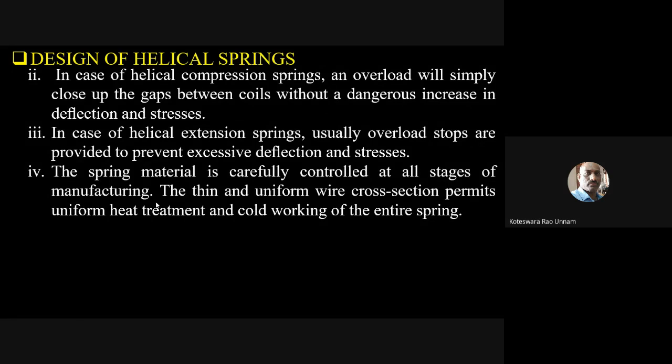So, generally we consider the factor of safety for uncertainties. Uncertainty may be in the determination of the load, maybe uncertainty in the homogeneity of the material. So first case we already discussed, that is the load, the uncertainty in calculation or in determination of exact load, what is going to act on the spring is going to be less in case of the springs. That is the one reason why we are using the low factor of safety.